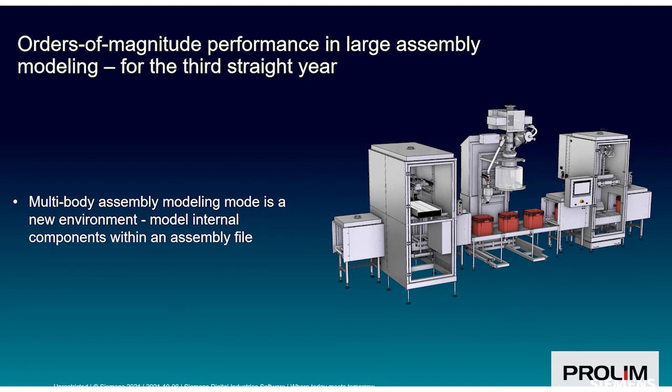So another additional really cool tool that we have is the new multi-body assembly modeling mode that creates and edits components within a file. Internal components live within the assembly file, so no part files are created on disk. Multiple internal components can be edited together, and this works with synchronous or ordered mode for parts and sheet metal. So let's go ahead and look at this real quick.